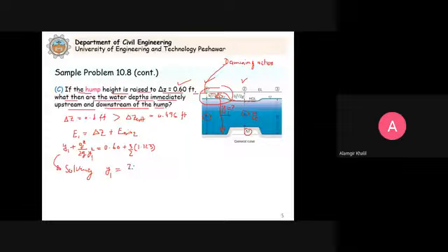So now this will be equal to 2.13 feet. This is one solution to the above equation when you solve, or this can be equal to 0.660 feet, and the third one will be negative, that is minus 0.504 feet. So now negative depth is not possible. So since damming action occurs, the water depth will increase because of the damming action.